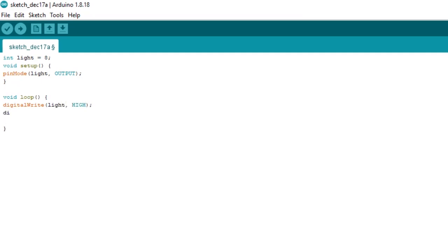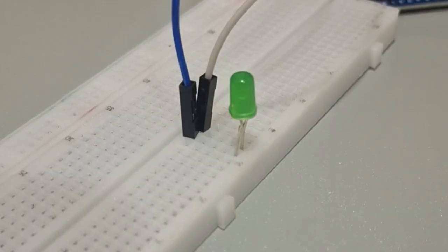Through this code we say when to transmit information and when not. When the information is transmitted, the LED will light up. When it is not transmitted, the LED will not light up. Now if we write the instructions under each other, we will not see anything because it will be done instantly. For that we need to write the delay code, which means wait, and in the brackets we write how long it should wait. Let me say that it is measured in milliseconds. So if we want it to wait for 1 second, then in the brackets we need to write 1000. This is the project.